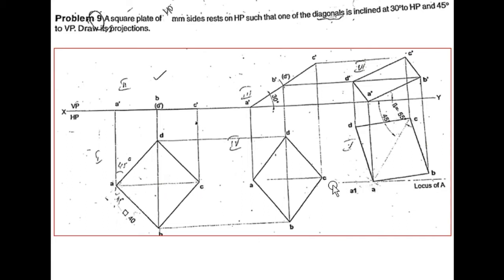After that I will draw the locus line. Next, from the same C point I will measure the distance C and A and cut an arc. This CA representation line is extended up to the XY line, and the angle which is obtained will become the beta angle. That is the beta angle. Right.